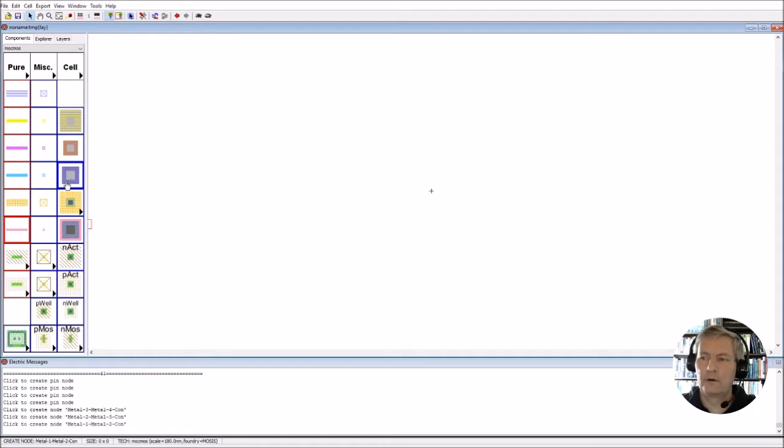And we've also got a via here from our metal 1 down to the polysilicon 1 and 2. Okay, so that's the connection from metal 1, that's the blue one here, down into these two layers. So all of what we see here are just the different layers and then the vias or the contacts that we can use in order to get between the different layers.